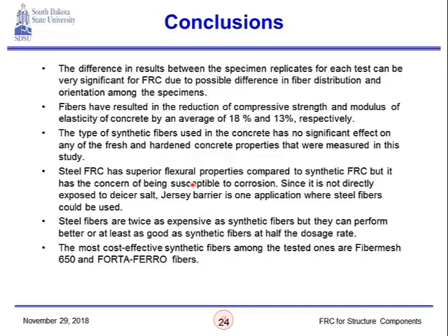Steel FRC has superior flexural properties compared to synthetic FRC, but it has the concern of being susceptible to corrosion. So this is something that we should always keep in mind whenever we're using steel over synthetic. But here we are just mentioning an example like jersey barriers, for example, since they are not directly exposed to ice or salt, there might be a good application for steel fibers.